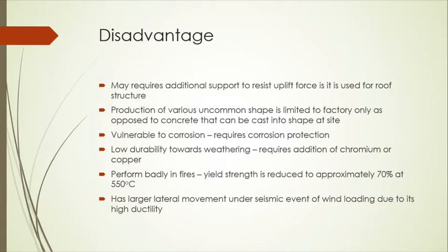To oppose the uplift forces due to wind, the dead load of concrete is enough to counteract the uplift forces. So the lightweight nature may be a disadvantage on certain structures.